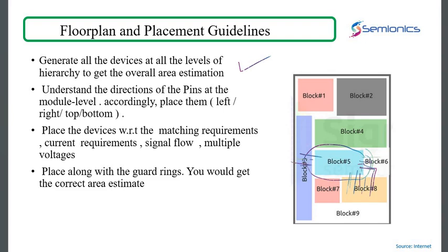So as I said, from the schematic point of view, you went and saw what modules are there. From the layout point of view, you need to ask your layout person who is doing the next level, where is my block sitting? How much area have I been assigned to do my block? Now he or she would have given some space for the other modules as well, along with the names. So then, based on that, you will decide where your pins should sit.